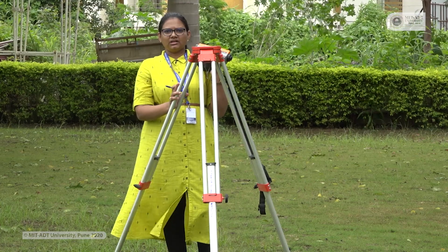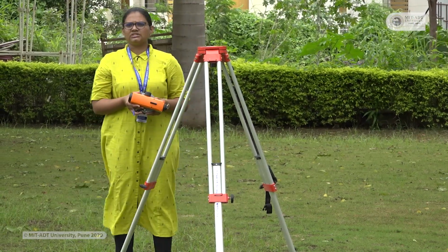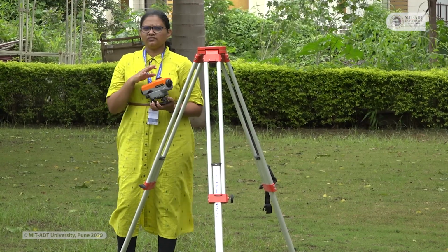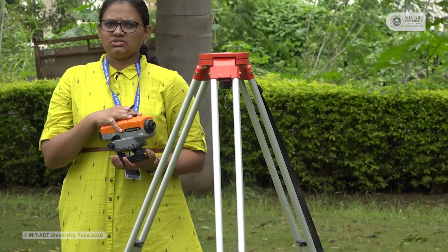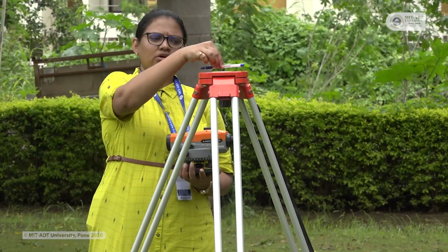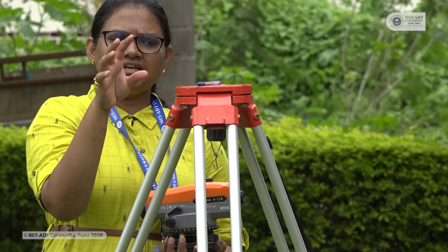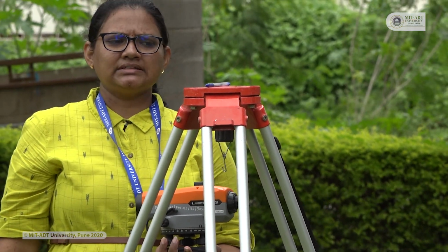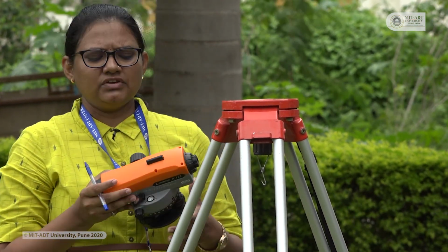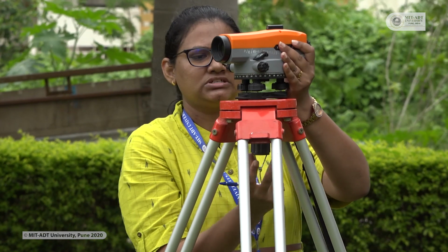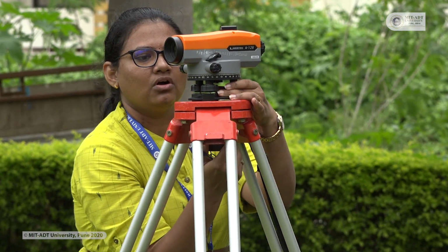So students, now we will take the reading by using this digital level. So we have to take different change points in this practical, and also we have to set our instrument on the field. So before fixing this instrument to the tripod, you can check the basics of the leveling. So you can use one pen. You can just roll down your pen on this tripod stand. If this pen has stability on this tripod stand, then you can say that your tripod is at the level. After checking this one, you can fix your instrument on this tripod stand. So I will just simply fix this instrument on the tripod stand.